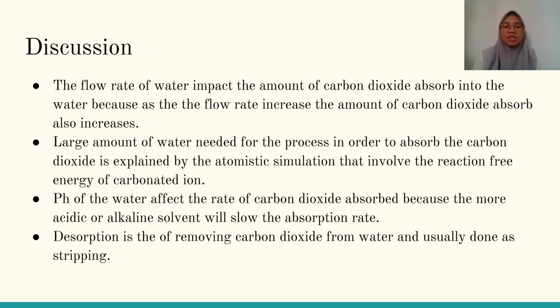The pH of the water or solvent also affects the rate of carbon dioxide being absorbed. As the solvent becomes more acidic or more alkaline, the rate of absorption decreases. Desorption is the process of removing carbon dioxide from water. In these experiments, it is usually done as stripping.